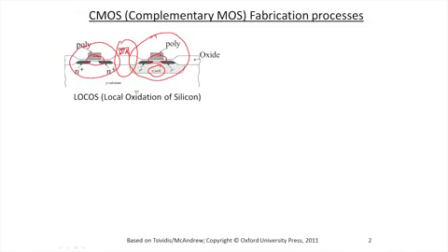But by separating the metal from the substrate by a thick oxide, by all this distance, you avoid this possibility. This characteristic shape of the oxide as it goes from thick to thin, for example here, is called the bird's beak. This process is rather old, and it has been used for many years in the industry.